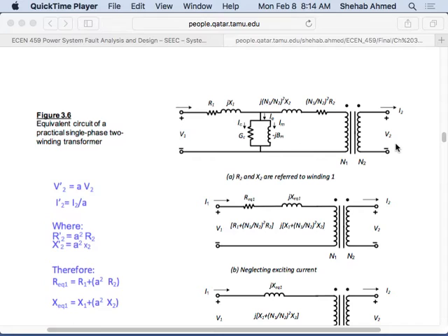So typically power devices or electrical devices are rated based on how much heat they can withstand, really. I mean, fine, insulation breakdown is another consideration. So basically two considerations: insulation breakdown, or physics, and then heat. But heat is really the major thing. So if you put a short circuit here and you put full voltage, do you expect to see rated current, meaning the normal rated value of current, or something a lot higher than that?